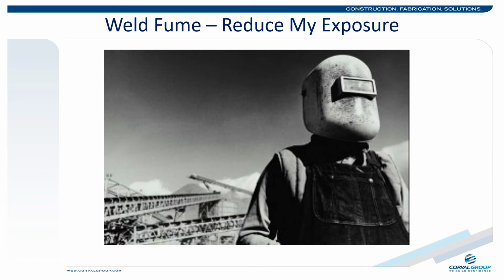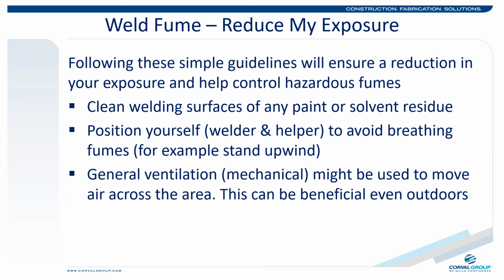It used to be said that you never see an old welder. Fortunately, today's welders are much more informed of the hazards associated with weld fume and are positioned to perform their work in a way that can and will greatly reduce their exposure with ventilation, respirators, design of welding hoods, and body positioning. How can you reduce your exposure?